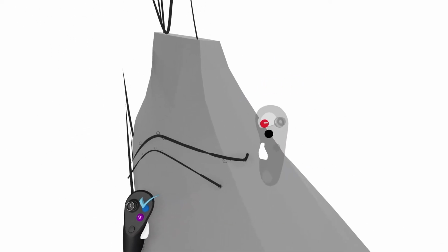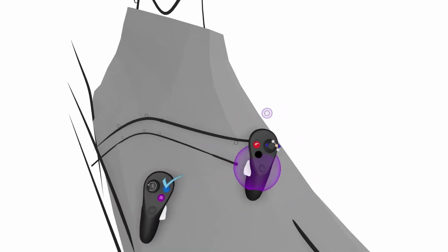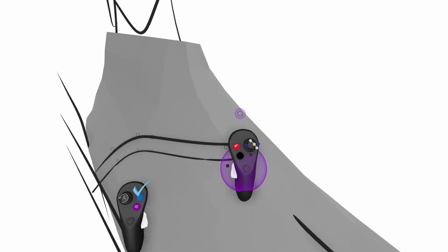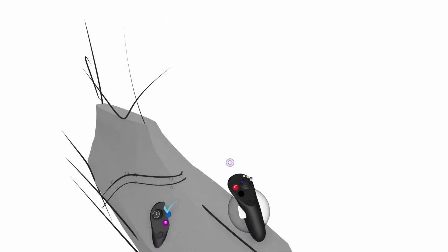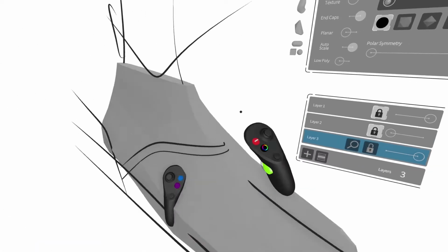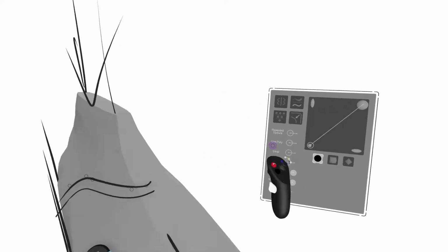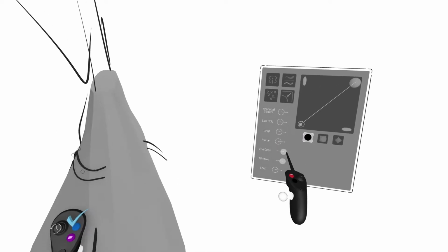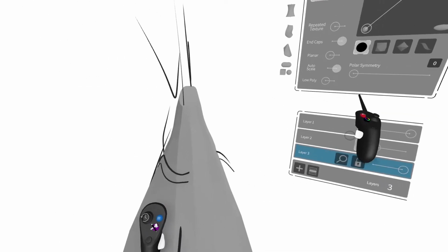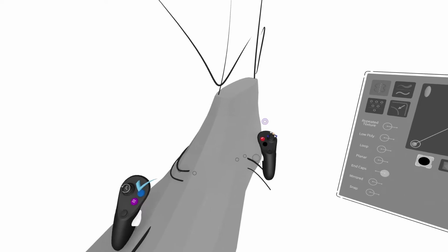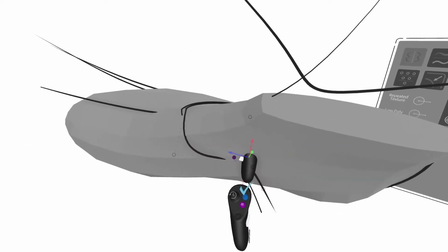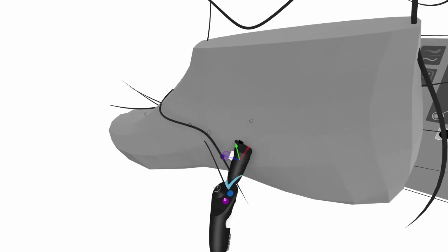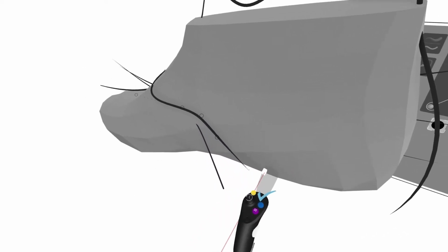And of course, where it's not symmetrical, no shoe is symmetrical. So one thing that we're going to want to do now is break that symmetry constraint. And luckily for us, we can do that in the edit panel. So what we'll do is now bake the symmetry, and now we have two separate strokes with their own points. I can start pulling that stroke out a little bit and give this the same type of treatment.